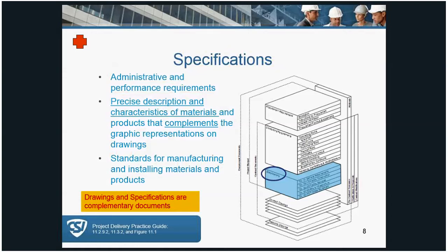So the basic steps, product selection. Again, you're looking at the products. How applicable are they? Is the manufacturer reliable? Have they been around in a while? Is the installation available? Is it tricky? Is it only certain installers can do it? What is the constructability of it? Does this have to be done in a dry climate when the factory happens to be in a very wet climate? And of course, cost is a big issue. Not only the affordability of the first initial costs, but also the overall life cycle analysis.